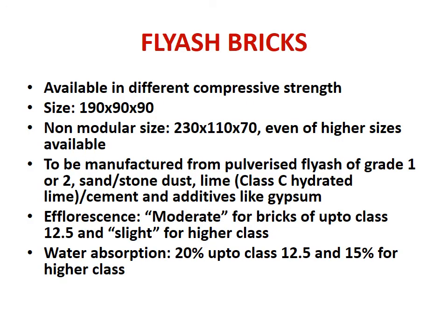Then let us talk about fly ash bricks. They are available in different compressive strengths, and they have better compressive strength than even clay bricks, and much better than AAC blocks, and they are available in normal size. Therefore, their handling is easy, and they are like clay bricks, not clay, fly ash bricks.